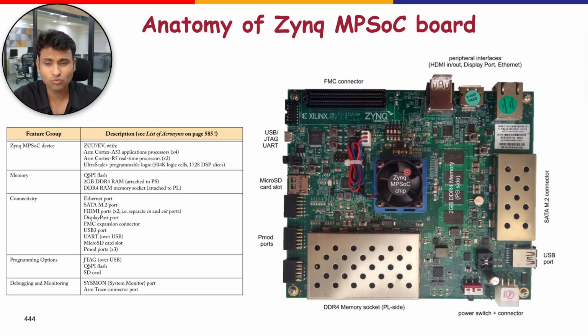Once we have designed our IP, writing the code in either HLS or directly at the hardware description language level, on top of that hardware there is a stack of software elements which may include one or more operating systems along with other application software and, if you have the RPU available, other real-time operating systems. In the following slides, we'll discuss the hardware design and the software stack in greater detail. But first we'll begin with an overview of the different elements that comprise a Zynq MPSoC system.